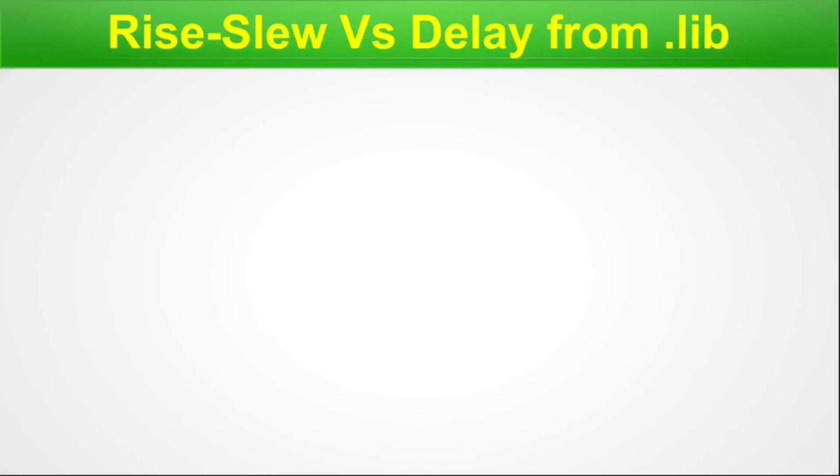In this slide, we will exemplify the lookup table for rise slew versus delay in NLDM model of .lib. Here you can visualize the 2D lookup table, LUT, from which the STA engine picks up the delay. In case an exact value of the index is not found, then the STA engine does the interpolation technique to find it out. Here the computational intelligence of STA engine can be observed. So let me bring up the details.